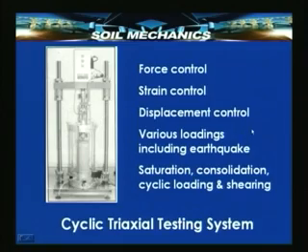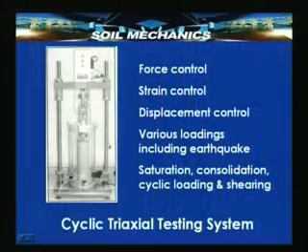The different types of loadings that can be applied can also be such as to simulate a given earthquake. A given earthquake loading, if you simulate and conduct the test under those conditions, the parameters which you get from this triaxial test will be the best that one can get in order to truly analyze the behavior of a soil under earthquake conditions. The equipment has the facility to saturate the sample, to consolidate the sample and to apply cyclic loading and then finally to shear the sample. That is what the cyclic triaxial testing system is capable of doing.